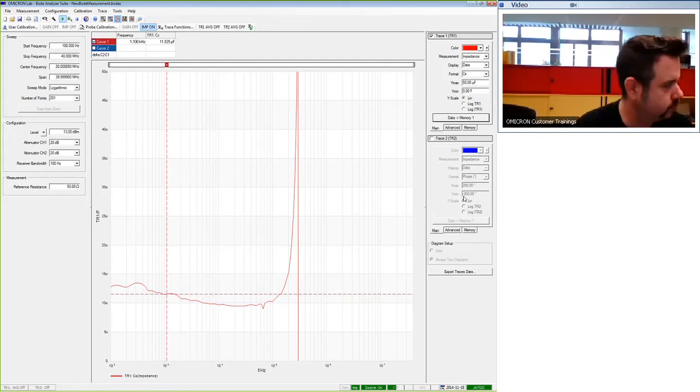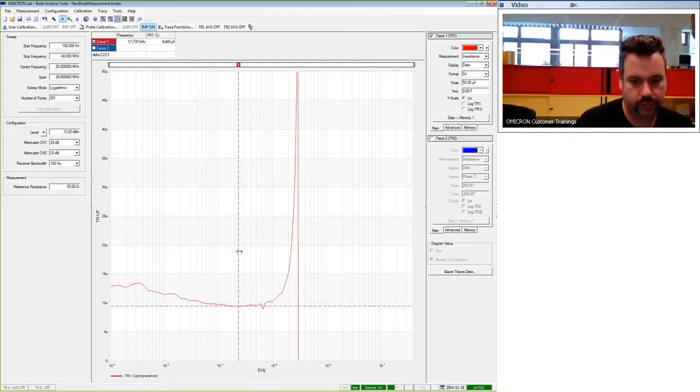But for now, since the time is running out, we can just mention that these bumps are caused by the probe calibration, and that the correct values are always at the low points, so at the lower points of the bumps. Okay. But we can also go to a higher frequency where it doesn't matter anymore.